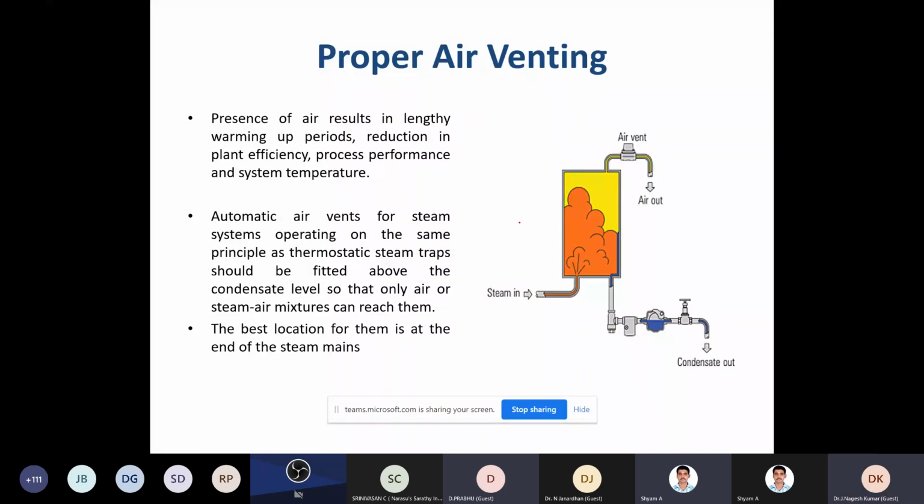So what we do is we don't put the pressure cooker whistle, the weight valve, immediately after starting the stove. You wait for some time, allow the air to go out, then you put the weight valve. You will find the cooking time will be faster because the air is vented out and you have perfect heat transfer. So cooking time reduces.